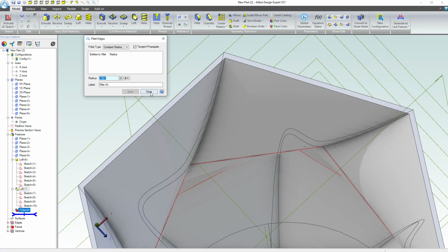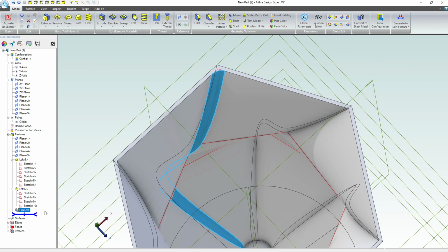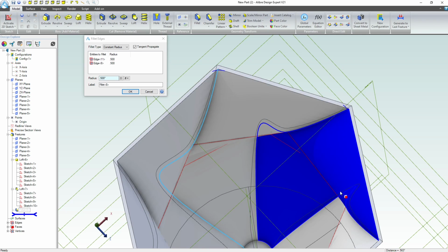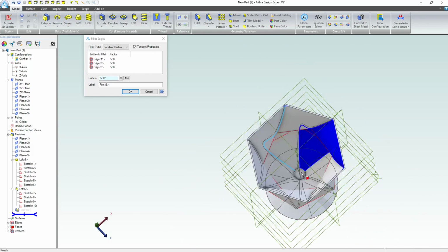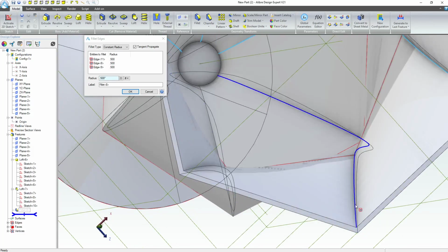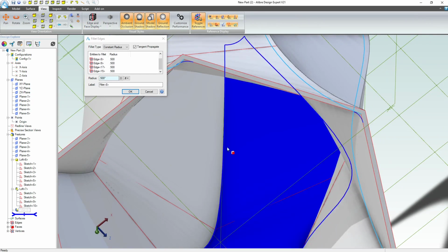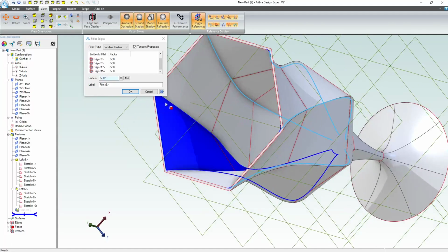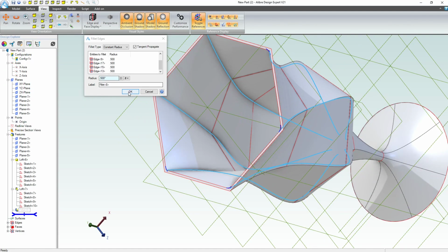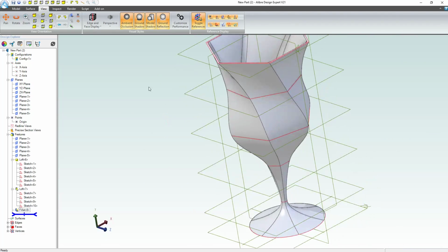Nope, we erred out on that one. So let's try a different one. Let's try 0.5, works. I'm going to edit this. We're going to add this edge. Right, and I can go around and choose every internal edge. I think my shaded with all edges is throwing me off, so I'm only going down to visible edges here. So that should be all of our inner edges. So we're a little bit more smooth on the inside.